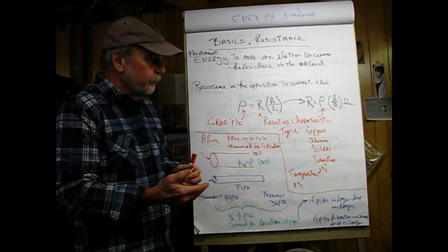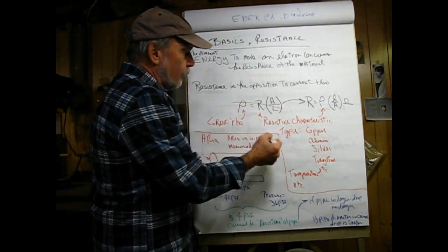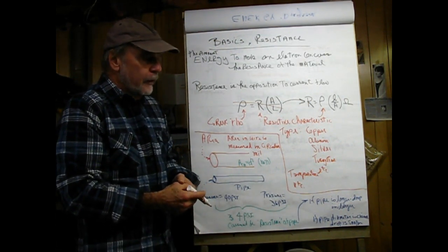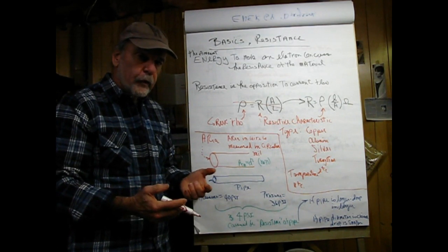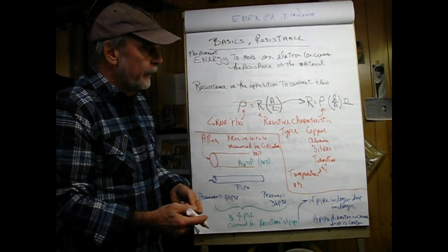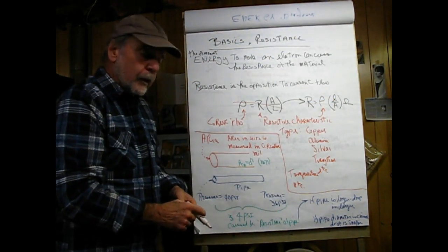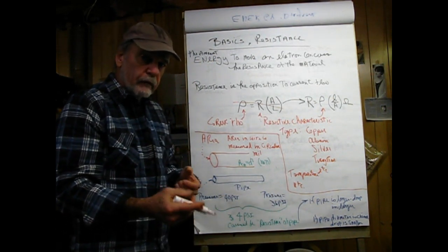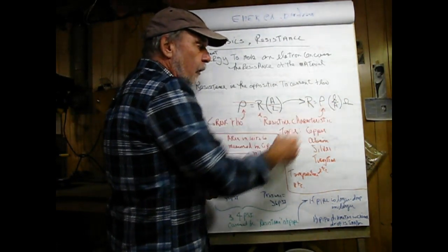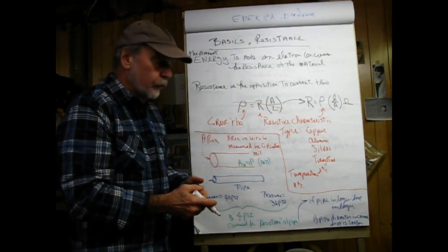And if we look at the formulas that sit under the hood on this, if we have this symbol here, it's a Greek rho symbol. That's the characteristic resistivity of the material, say that be aluminum or copper or silver or gold or whatever. And then we see that it's multiplied by the length divided by the area. So the longer a wire is, given a constant area, the more the resistance, and given a constant length, the thicker we make the wire, the larger the cross-sectional area, the lower the resistance.